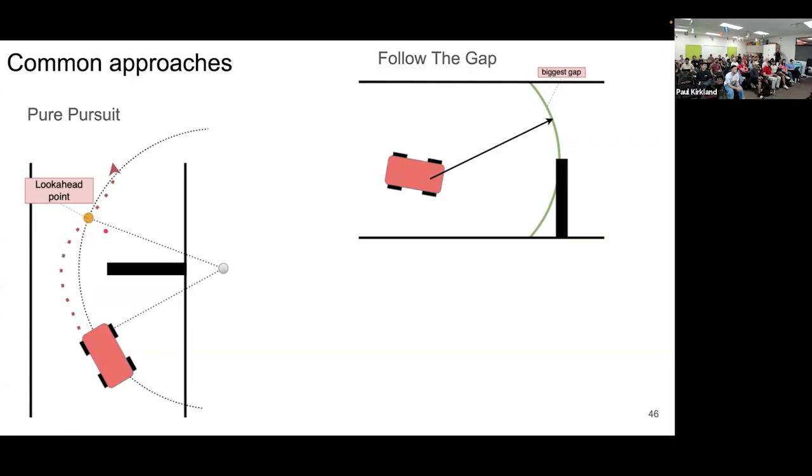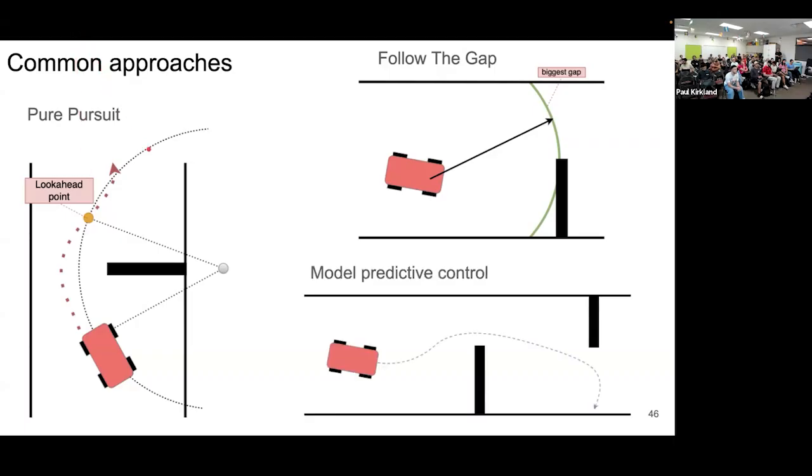You can also play around with that. There are a lot of engineering tricks you can do, for example, selecting the look ahead distance. That's not trivial. When you're fast, you want a longer one. When you're slow, you might want a shorter one. It's all implemented in the simulator already. I talked a lot about MPC, and I finally tried to illustrate what it is, for the people that don't know, on the next slide.